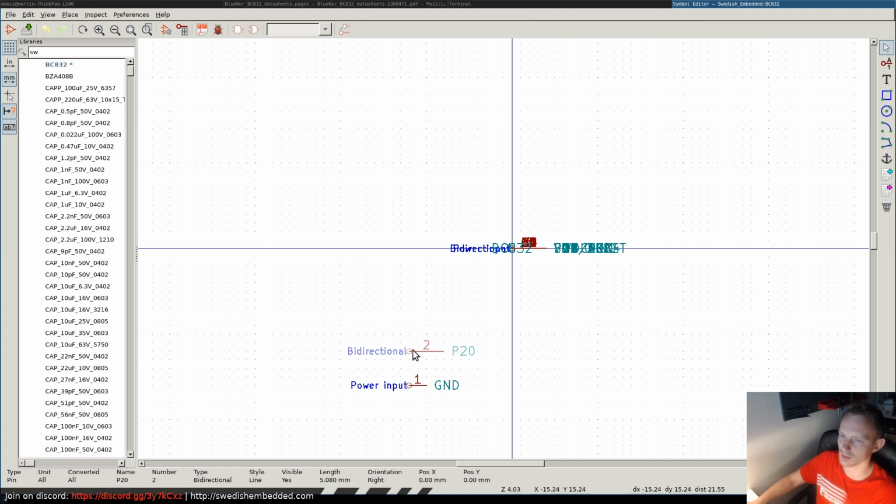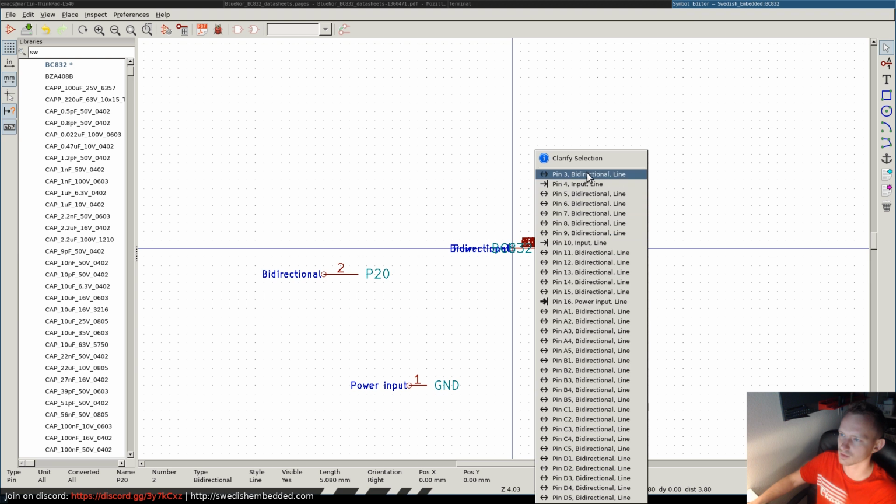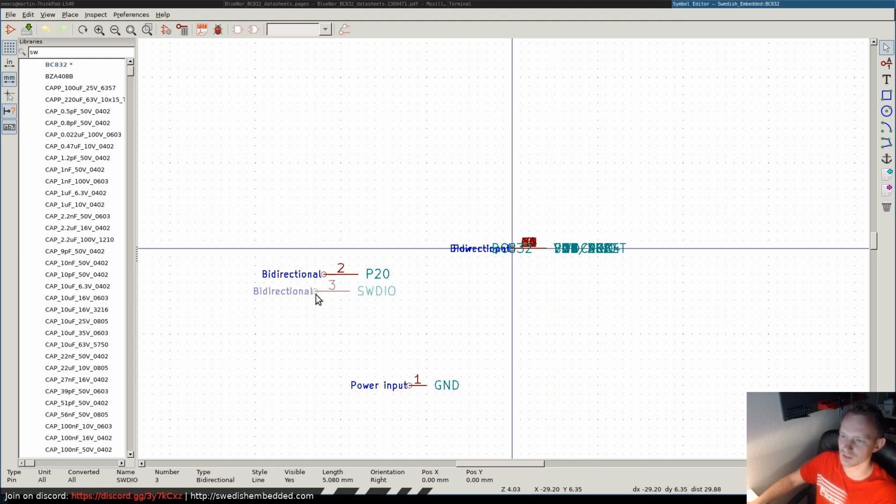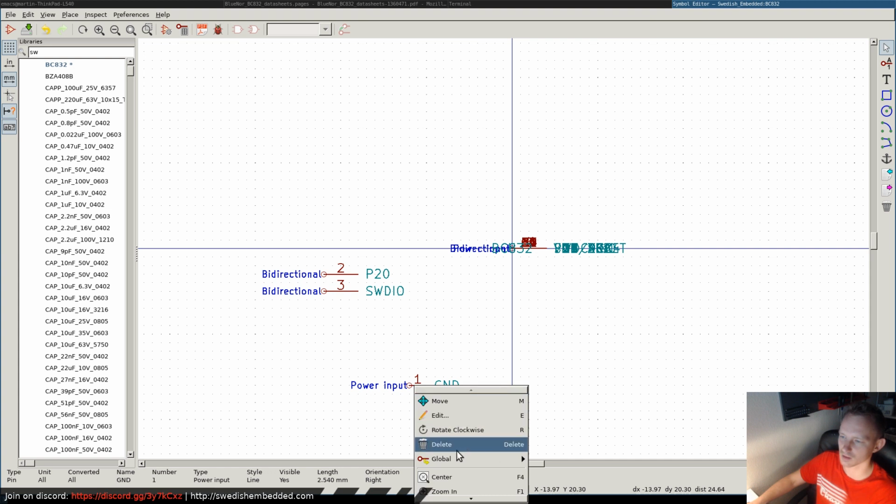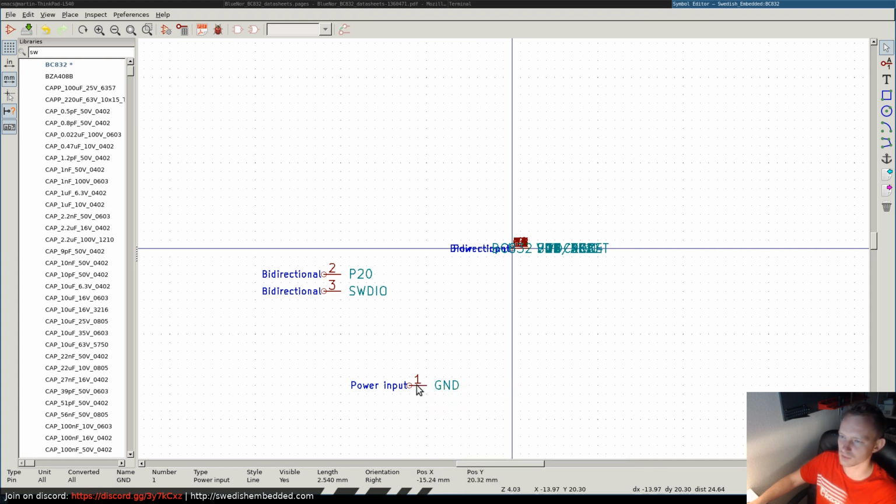So right now, let's just, I wonder if there is any. Oh, actually, I'm going to do it like this. Global push pin size to everything. This is very useful. You can change the size on one pin and then just push the size to all the other pins.